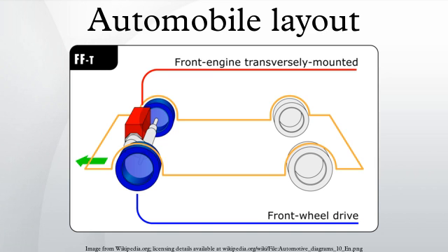The layout of a rear-wheel drive car is much closer to an even fore and aft weight distribution than a front-wheel drive car, as more of the engine can lie between the front and rear wheels, and the transmission is moved much farther back. Weight transfer during acceleration. During heavy acceleration, weight is placed on the rear, or driving wheels, which improves traction. No torque steer.